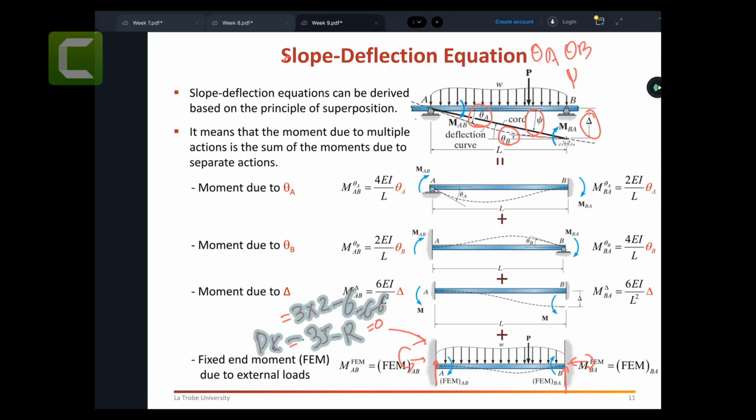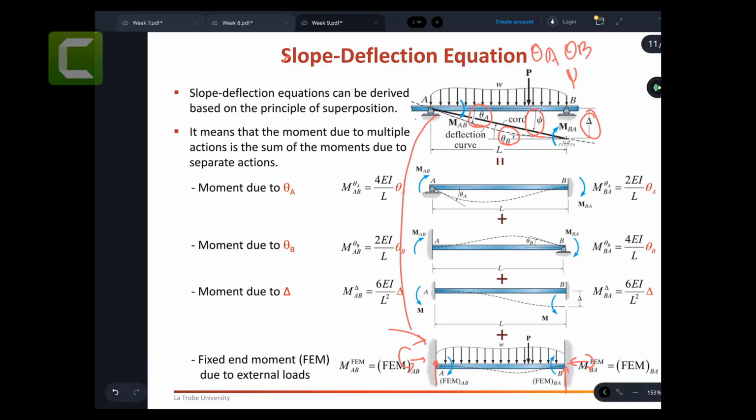So you can see that if it is 0 kinematic degree of indeterminacy, meaning that the structure is determinate, right? So what I want from here to here, I make the structure first kinematically determinate. Initially it was kinematically indeterminate by the degree 3. You can see theta A, theta B, and psi. So what I did, I come here and put two big clamps, meaning holders. I go in the beam, put the clamp and make that one fixed. So when I make this clamp, then it becomes a kinematically determinate structure.